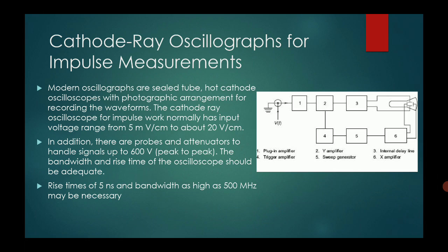The bandwidth and the rise time of the oscilloscope should be adequate. A rise time of 5 nanoseconds and a bandwidth as high as 500 MHz can be necessary.